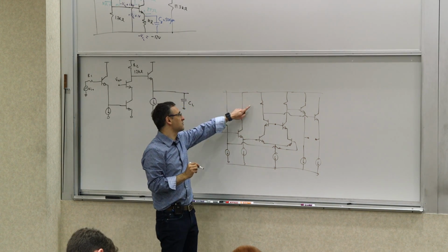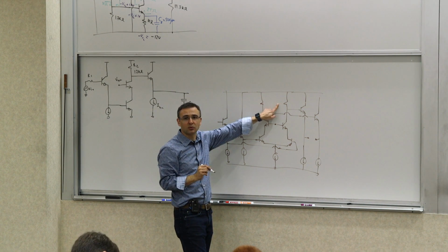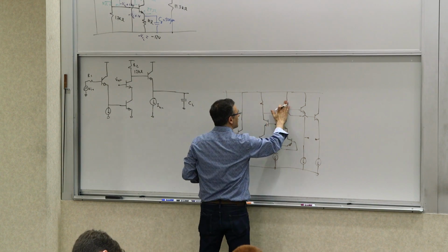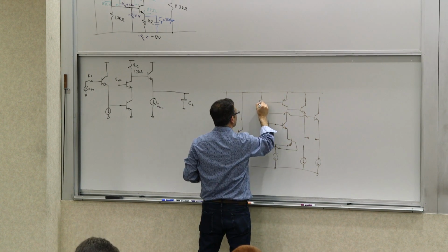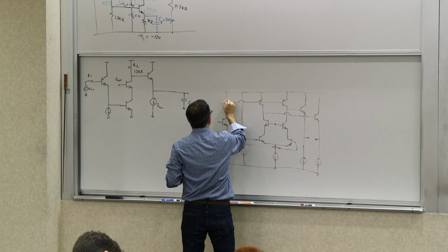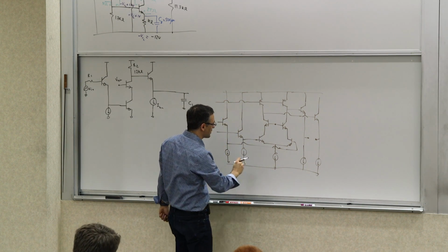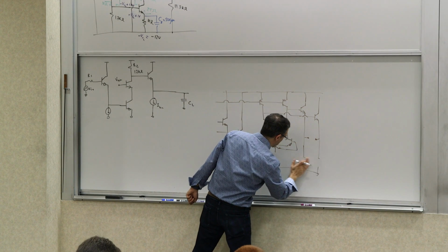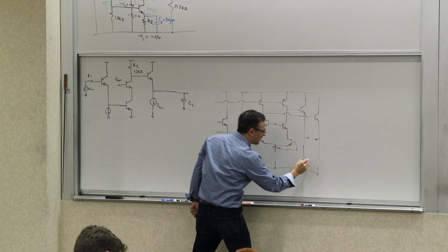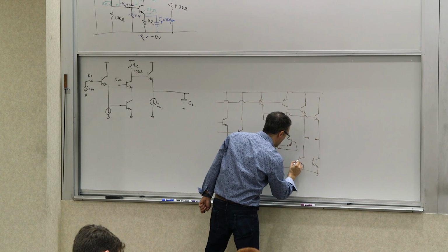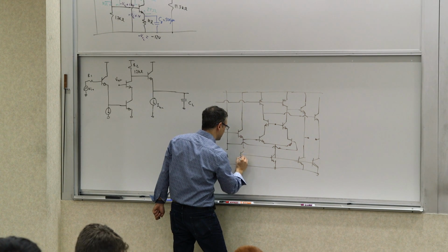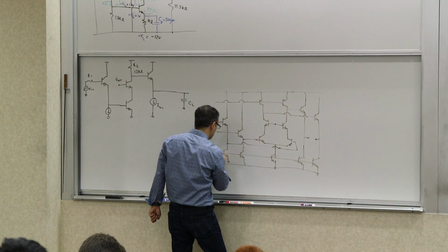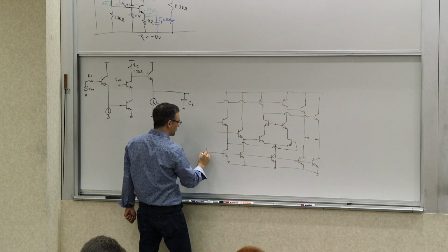If these resistors bother you, you can actually replace them with active loads. You can put current sources there. So for example, these could be PNPs, if you have decent PNPs, or if not, you can use other things. So these are basically current sources. You can replace these current sources with actual transistors to represent them. And then you need probably some sort of a reference branch.